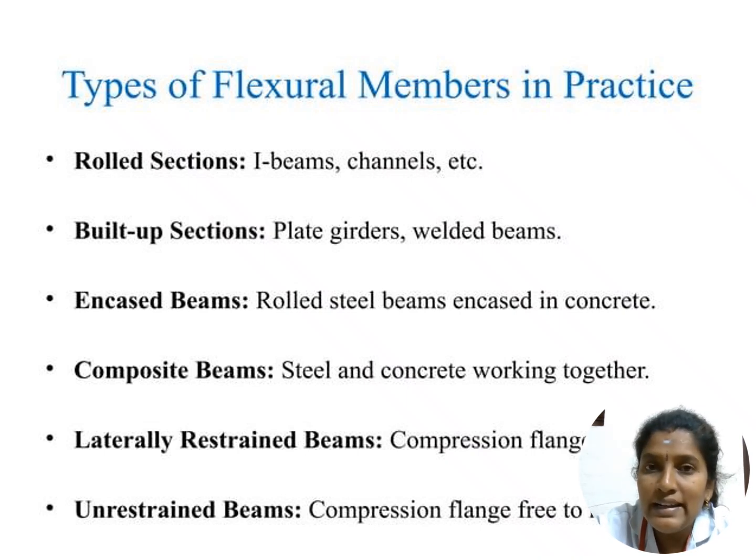Laterally restrained means there will be a reduction in the buckling. In the unrestrained case, there is no reduction, and there is free movement of the forces, right? So the compression flange to the tension and the compression will vary for the restrained condition and the unrestrained condition. We will see this later.